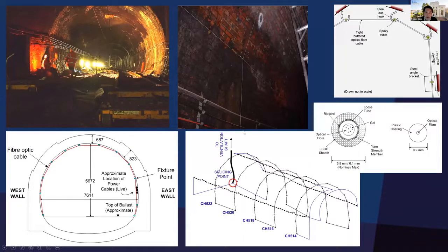So you can see the fiber optics over here. It's the early days, so we went to a DIY shop and bought this hook, and then we attached the hook, and then we put the cables around, and then pre-tensioned it, and then glued it so that we can measure tension and compression as a change in strain.